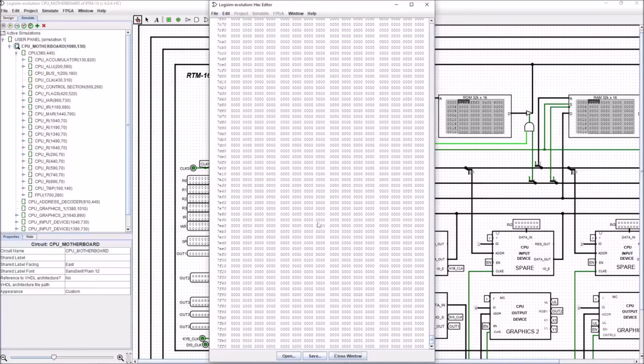So we need to know whereabouts in the RAM these temporary allocations are for the subroutines that are in the ROM, and we need to be careful that we're not overwriting them while we're in the middle of a program. It's just going to mess everything up. So there's lots of these little subtle things that occur that tell us that we really need to be careful about where we put information in our ROM and our RAM. And this is the reason why we want to have a memory map.